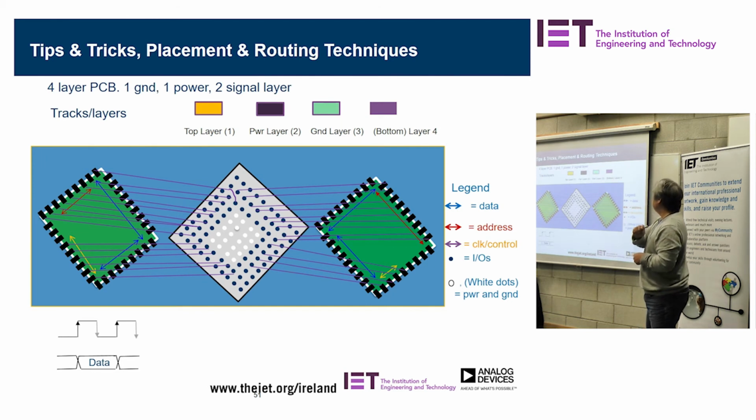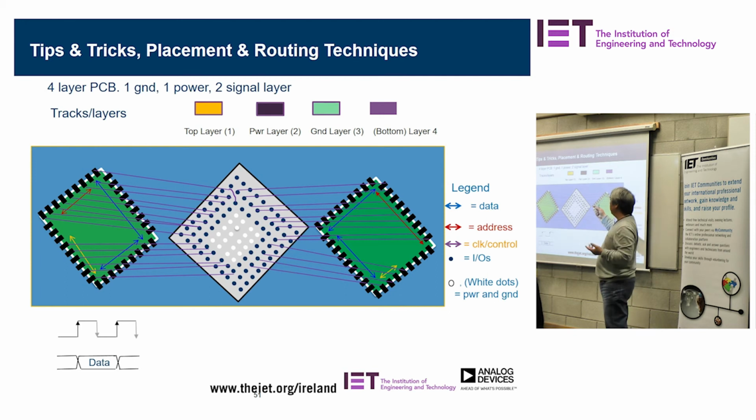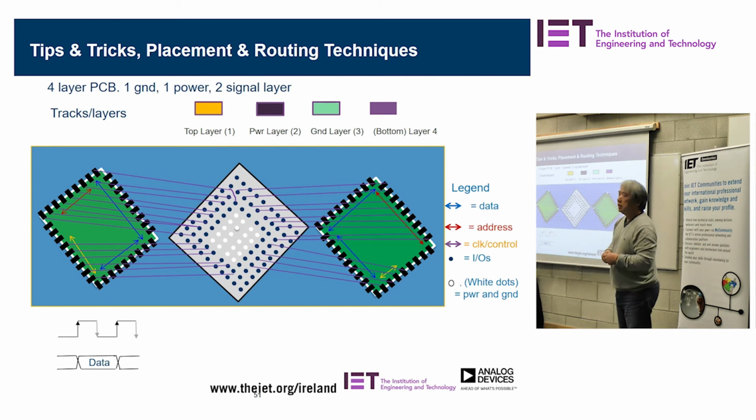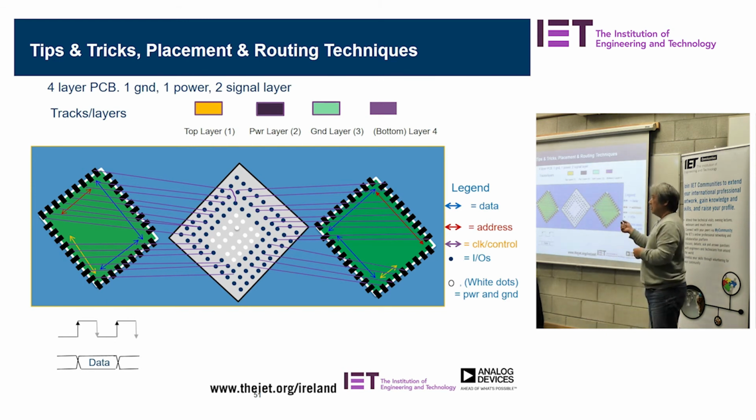Okay, so it works for differential pairs as well. It works for parallel interfaces. It works for a differential pair if you have a pair. So you only have a small difference of maybe 1 mil. If you want to tidy that 1 mil difference, you have to curve it a different way to give you that 1 mil extra line, you know. But usually 1 mil is not a big issue.